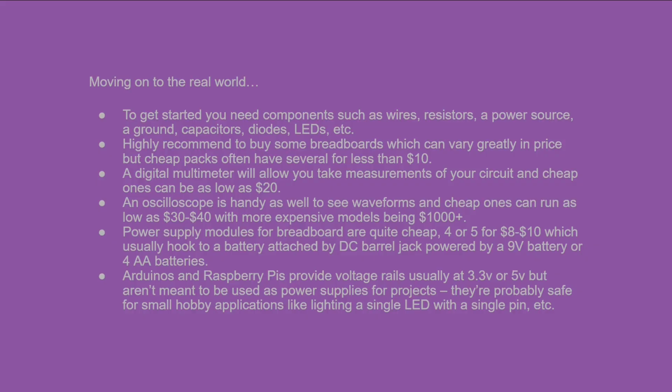There's examples out there that have you just get a battery connector and just shove wires like that. I don't really like going with that. Although if you do that with the USB cable, the adapter handles a lot of the stuff that the module does, but I'm not a big fan of just plugging a 9-volt battery with two wires into a breadboard. If you have Arduinos, Raspberry Pis, whatever, because a lot of these kits may come with something, you could technically use those as a power source because, again, it does everything that a power supply module does. There's issues, limitations, and caveats with that, so be careful. But if you're using it for really simple circuits, like to kind of simulate Ohm's law, you shouldn't have to worry.